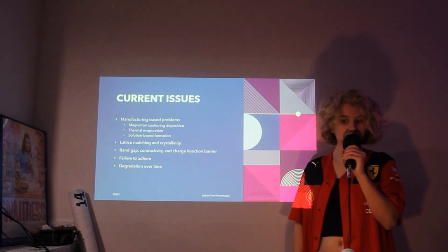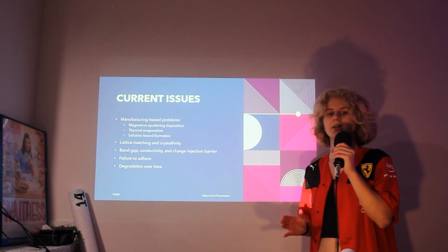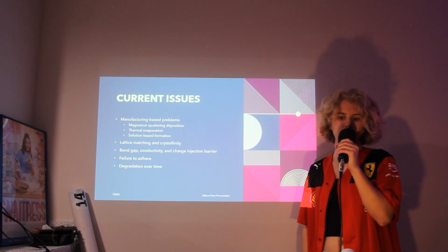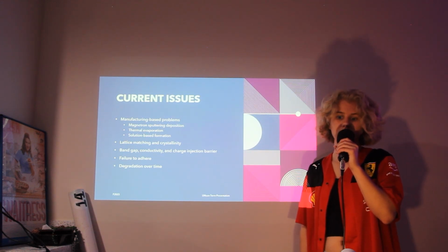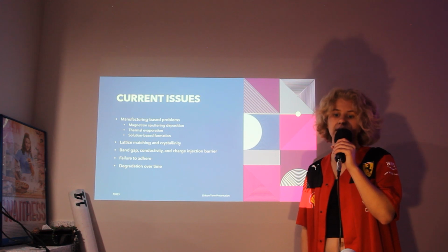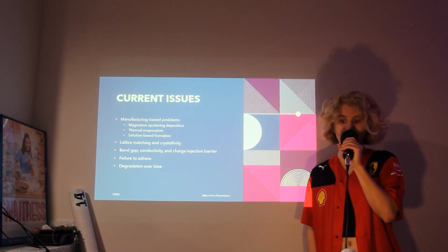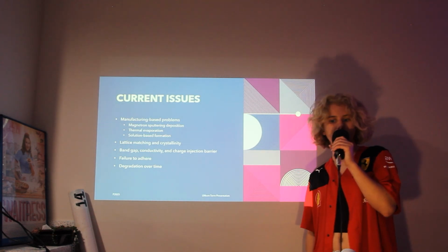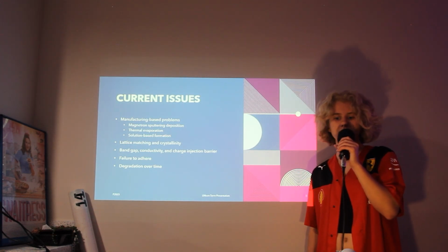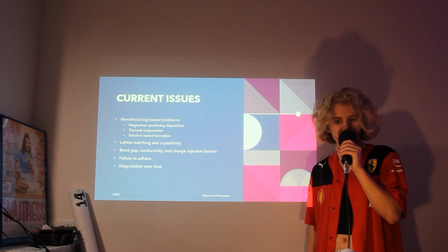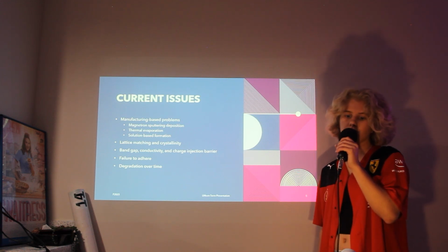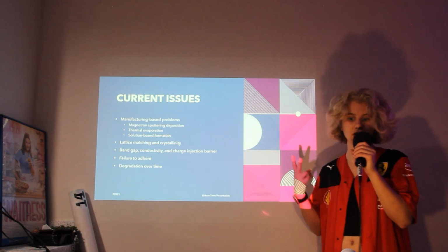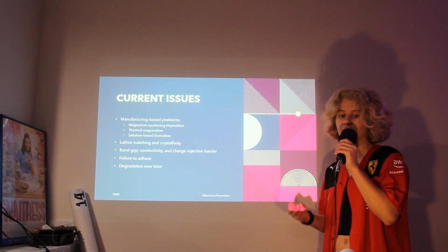According to a 2021 paper out of Loyola Chicago, contact deposition routinely leads to thermal damage to the organic material and often penetrates through the organic layer. In other instances, metals fail to wet the organic surface, leading to a discontinuous film when thin metallic layers are needed for transparent contacts. Other prominent faults include contact delamination, charge injection barriers, and susceptibility to degradation.